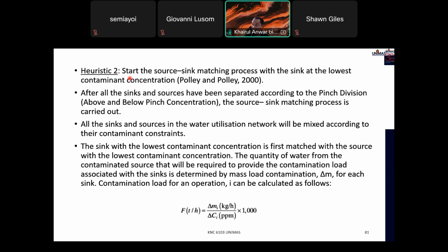Once we identify the pinch, then we can use the minimum fresh water needed based on the pinch point as the fresh water flow rate. So the second characteristic must start at 0. The same thing for the diagram before you do the shifting.